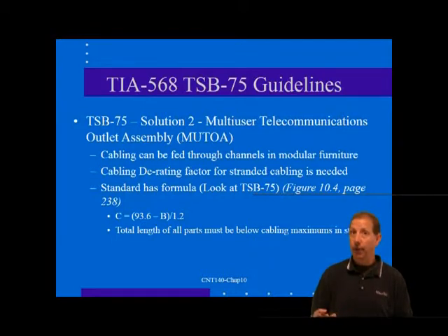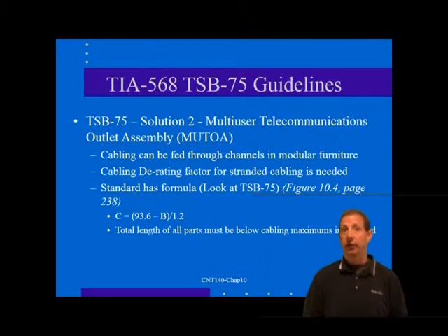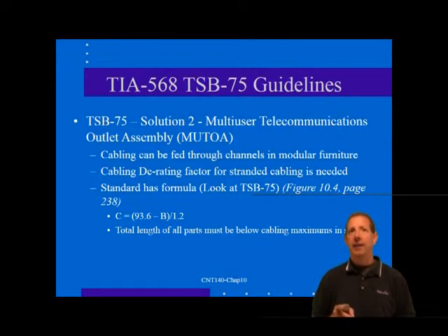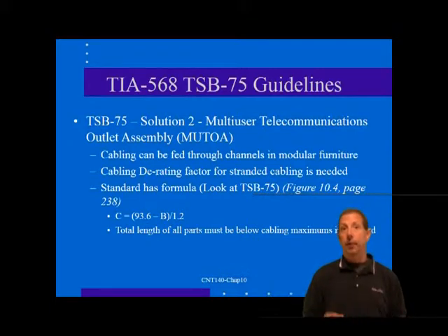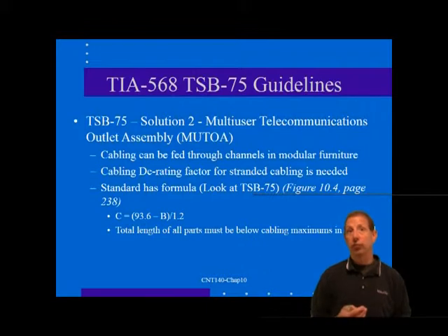Also, the electrical power to the module should be turned off for safety reasons during the installation of the cable into the module. Note that there is no workstation outlet in the normal area of the workstation. The work area outlet is in fact part of the multi-user outlet assembly that serves all the nearby modules. The extended user cord is run through the modular furniture and plugged directly into the user workstation.